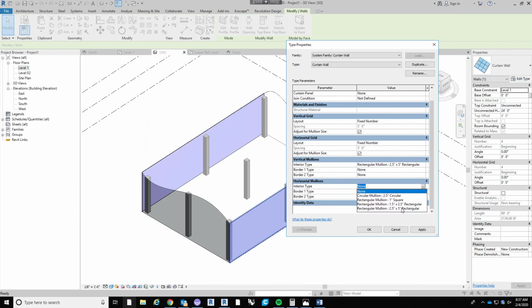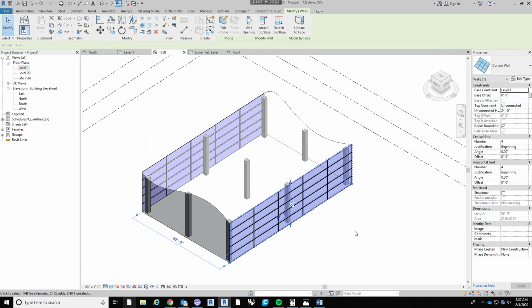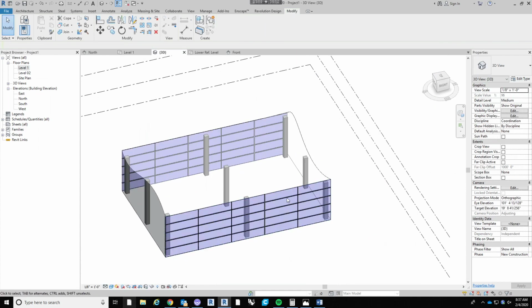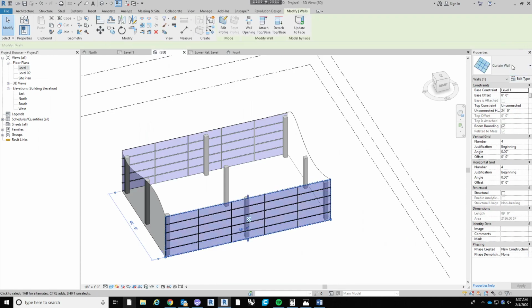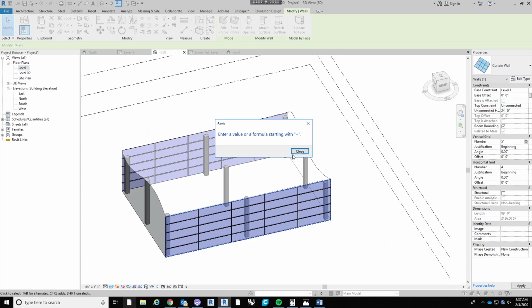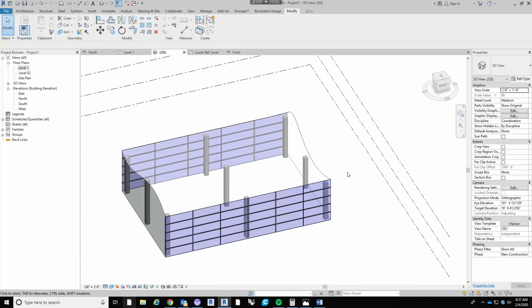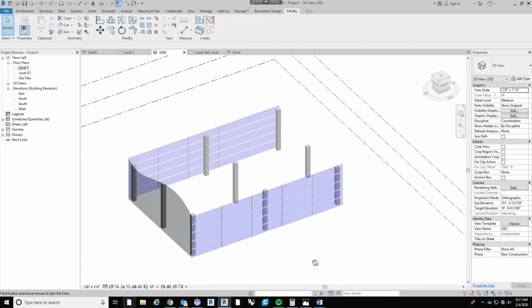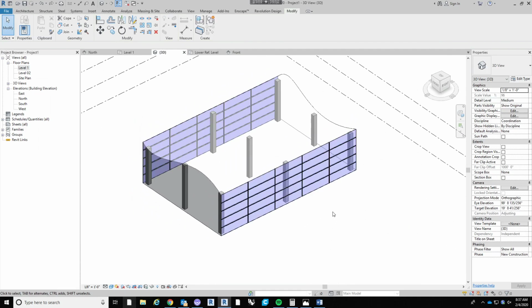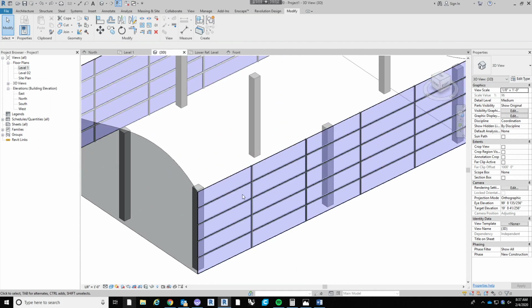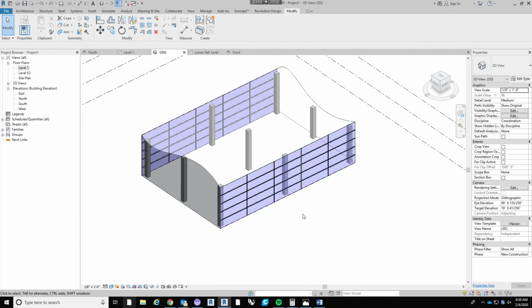2.5 by 5 for the interior of the horizontals. And press OK. Alright. So now remember, when we do fixed number, those numbers that we can manipulate are at the instance parameter under properties. We can change that. And make sure you don't put any units in there. And it will change that specific wall into a different spacing. So let's go in and manipulate this guy.